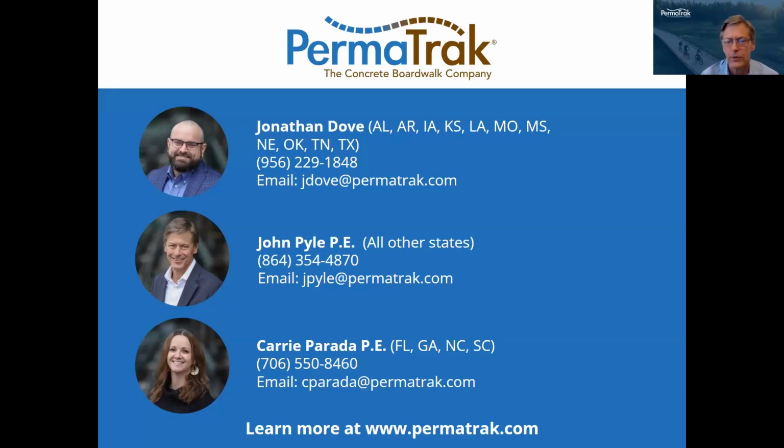So that's one consideration when you're around water. The other consideration is, if it's a salt environment, you may want to consider using epoxy coated steel instead of standard black steel. We've supplied that on a number of different structures. And because you are around a river course, water course, permitting may be an issue. So you need to think about your access. How much can you permit? What's the impact? What are your working points? What's your access? Those are all concerns.